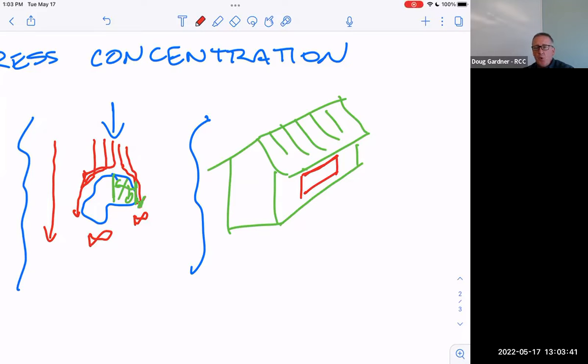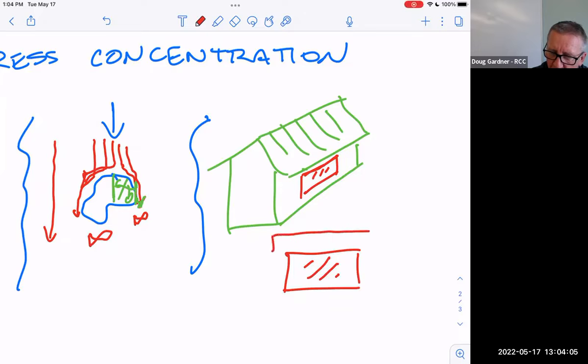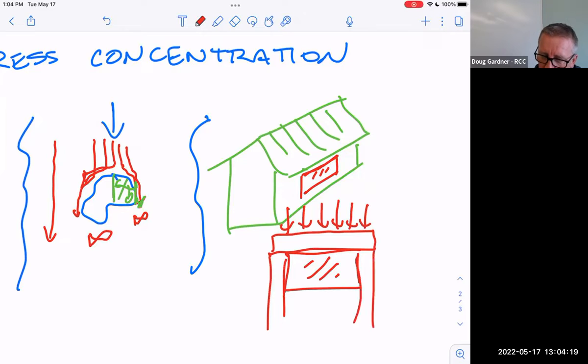The answer is no, because glass is not going to hold weight, and you've now made it so that there's sort of a spot that can't hold weight. So how's that supposed to be held up? How's that window going to be held up then? What happens inside of a house? Do you know this? So here's your window. You basically have to throw a beam over the top of that window so that all of that load coming in from the roof sits on that beam. And of course, in order for that beam to not just rest on the glass, you've got to put a post over on this side. So that's called a post and beam structure.